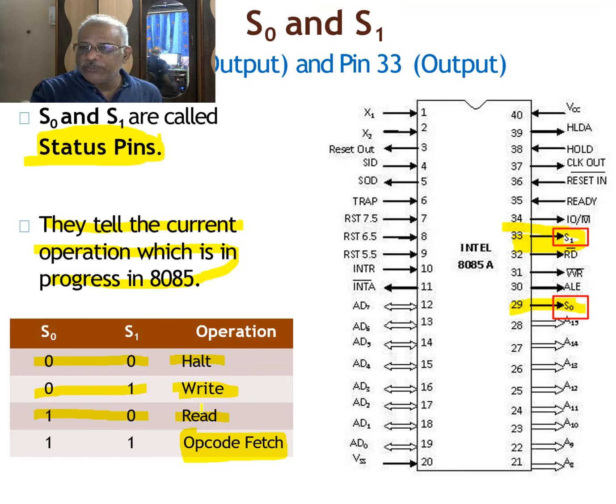and the last 4 bits also form a nibble, and we can convert those 4 bits into a hexadecimal number, which we discussed in the first semester. So the 8 bits, as 4 bits each, are converted into hexadecimal numbers. So each and every instruction is given a code as a hexadecimal number. So each operation is given a hexadecimal number, that is called the operation code, and that operation code is given to the microprocessor.